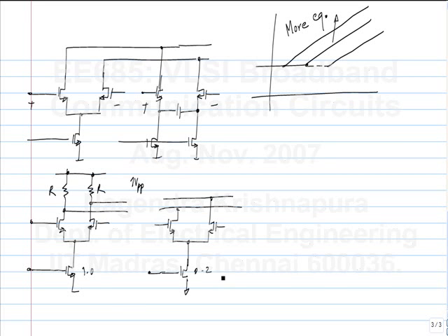Essentially, this is an equalizer with coefficients of 1 and minus 0.8. Sorry, minus 0.2. What will be the output value if you apply a DC step? The coefficients are this. If you apply a series of ones, what do you get at the output? 0.8. Yeah. So you get a reduced amplitude, but some equalization.